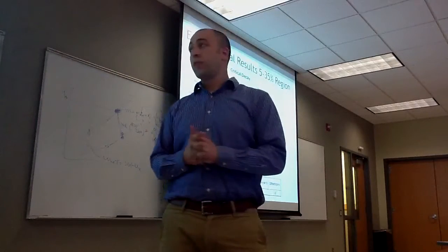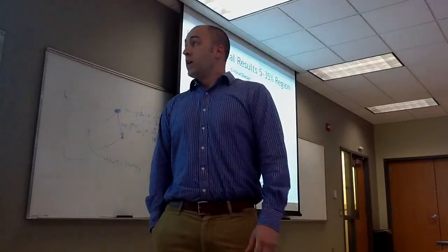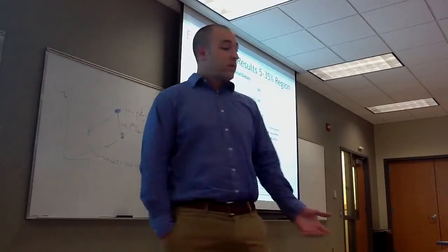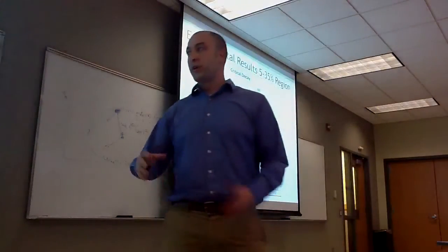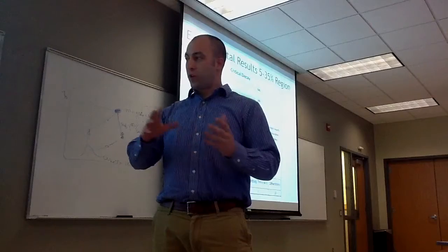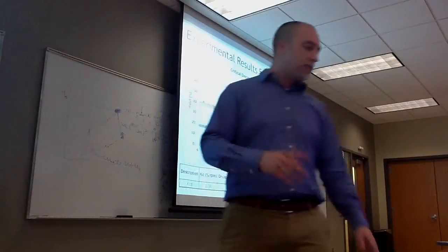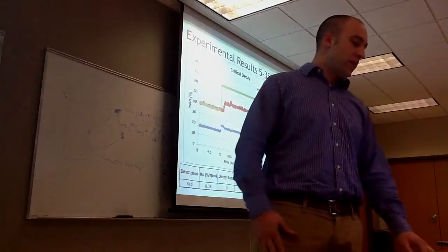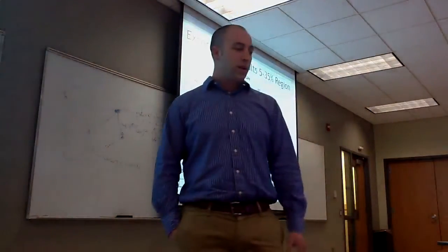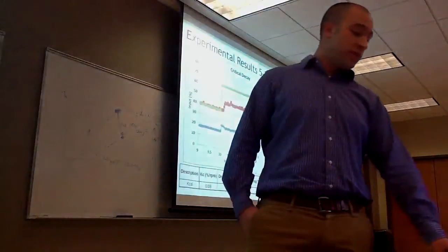Here's the graph for critical decay. I found the gain to be 0.03, which is tricky because the smaller regions are almost all alike, so I had to zoom in and determine which one was best fit, so it's a ballpark estimate. It's monotonic and it has an offset of 130 RPMs.